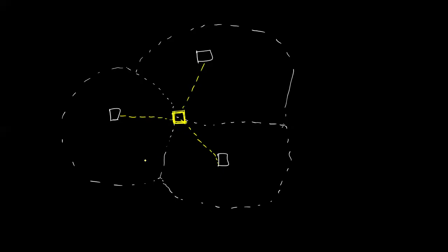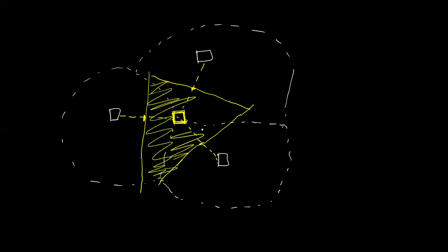Now where is the service area of this newly constructed substation? So how is it decided? From this yellow line, we draw a perpendicular bisector. So take half the length here and draw a perpendicular. Similarly, half the length here and draw a perpendicular. Similarly, half the length and draw a perpendicular. So draw perpendicular bisectors and extend them. Now whatever area is covered in this, that gives the new service area of the newly constructed substation.